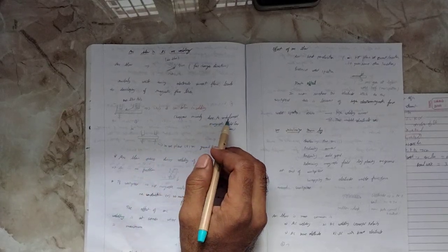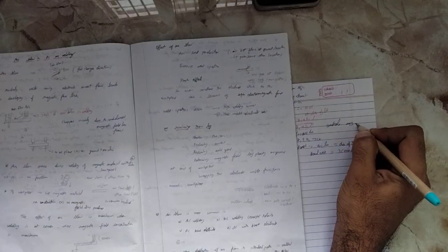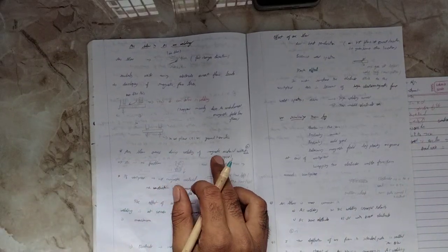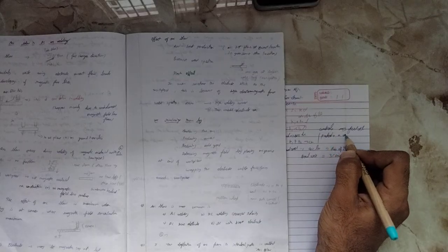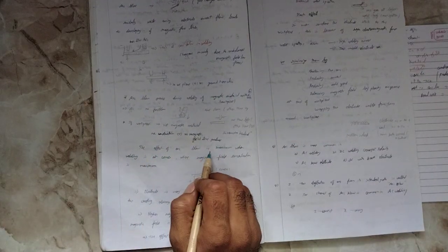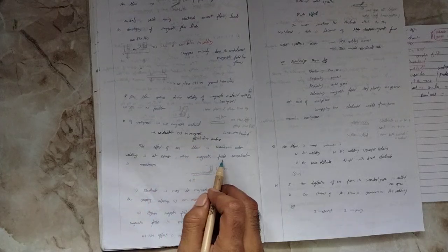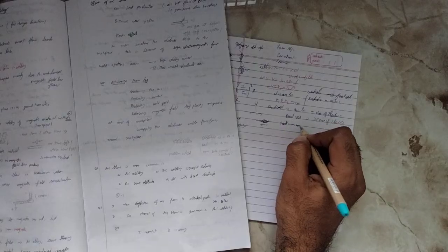You can see it happens due to unbalanced magnetic field lines. Arc blow occurs during the welding of magnetic material with DC. If we use magnetic material with DC, definitely this kind of arc blow will occur. If the workpiece is not magnetic, no magnetic field will be produced. The effect of arc blow is maximum when the welding is at a corner and when the magnetic field concentration is maximum. The electrode may be magnetic or not, but the coating is always non-magnetic.